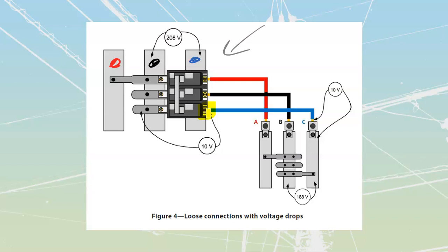I'm going to have volts that are dropped. I'm also going to create heat at that point. And as soon as I create heat, I am often going to cause more arcing, and things like that are going to continue to become a self-feeding type of problem. Any sort of loose connection right over here and a loose connection over here is also going to result in an imbalance in my values of voltage.